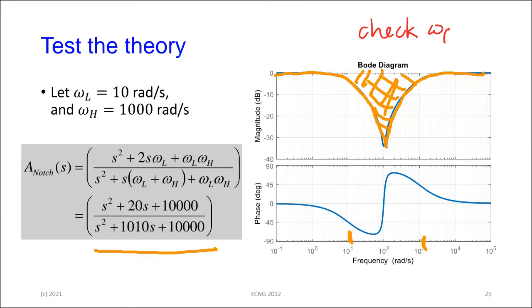We'll talk about that in a second, but that is one of the consequences of notch filters, that the phase gets very lousy. But the behavior, which is the frequency response, just by putting a low pass filter and a high pass filter, a simple first order low pass and a simple first order high pass in parallel, we have created a band reject filter. And the arrangement, how you derive the transfer function and how you implement the transfer function is very straightforward. It's not complicated at all.